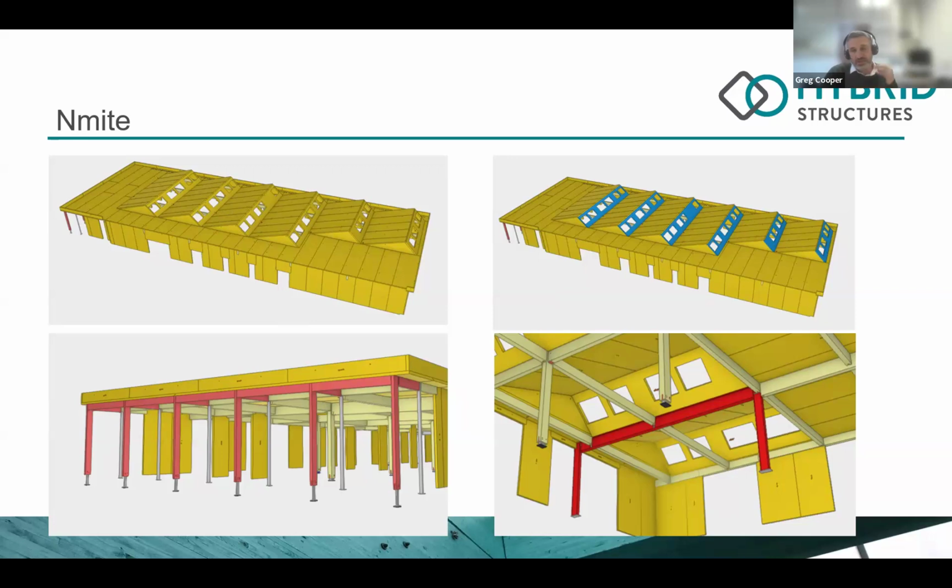So the maintenance strategy was there, the long-term CDM requirements of the building were taken into account, so it could be replaced. And like we spoke about, the width of those was absolutely key. The thinner it is, the quicker they need to be replaced. So during the life, we've estimated they probably need replacing every 10 to 15 years by the client, just to make sure they're getting the maintenance and the long-term life out of them. So the whole design, how it clips together, was vital.